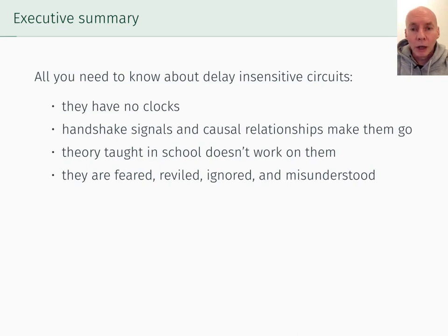They have no clocks. Does your computer run at 4 gigahertz? If it were delay insensitive, that would be a meaningless question. It would run as fast as it runs. Because they have no clocks, different parts of a circuit have to coordinate with each other by sending a signal that says, "Are you ready? I'm ready. Good, then we're both ready." That exchange is known as a handshake.